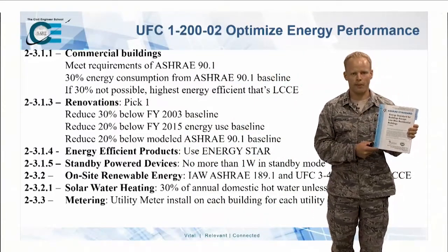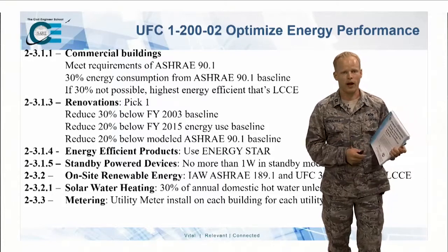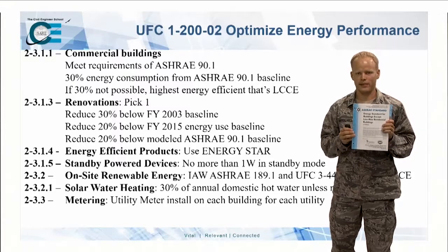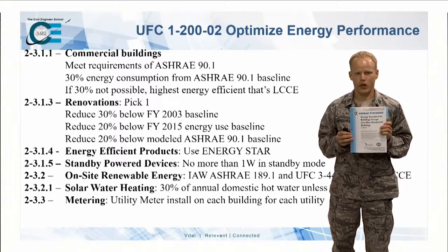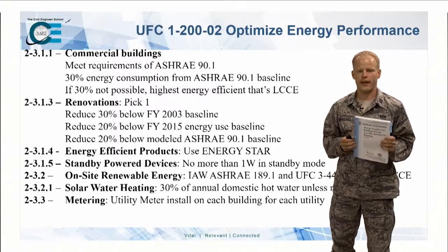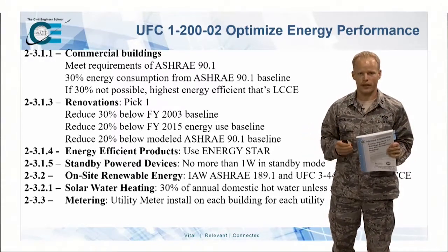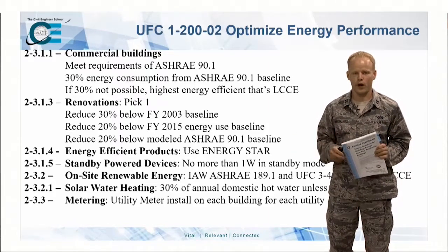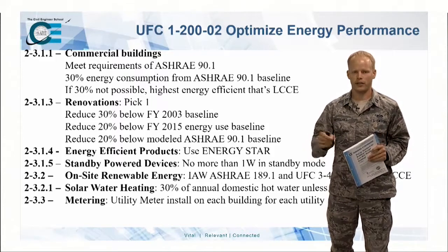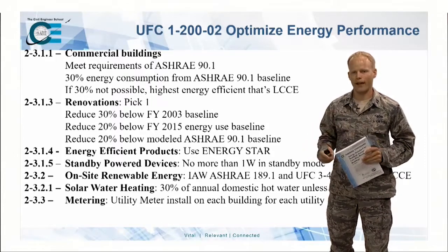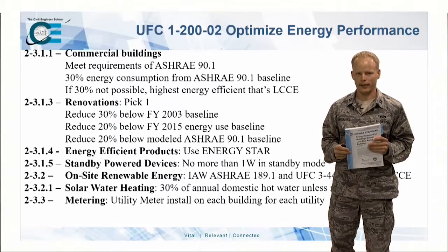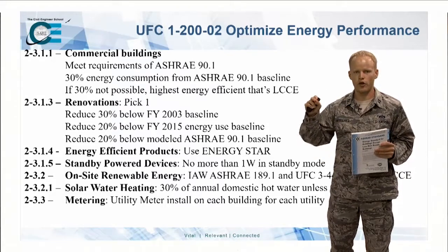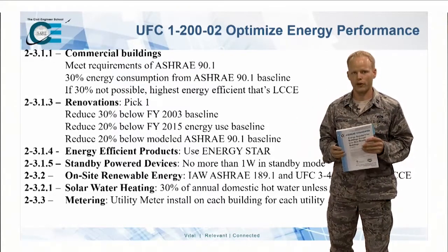But the 90.1 baseline, we'll talk about that in a moment, is a building that is prescribed by here saying you should be meeting these requirements at your given location. And that's where you start from. It's a baseline building, and it's not necessarily a real building. You're going to plug in values for walls that are in there, and you'd have to find the materials that match this to try to validate what this building would look like in reality. But a lot of energy modeling software goes out there and says, okay, what is the U value for the window? So on and so forth.